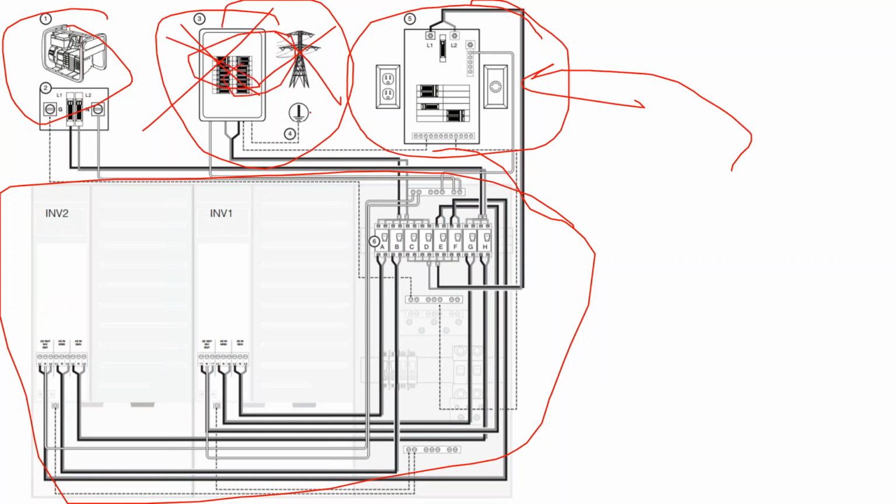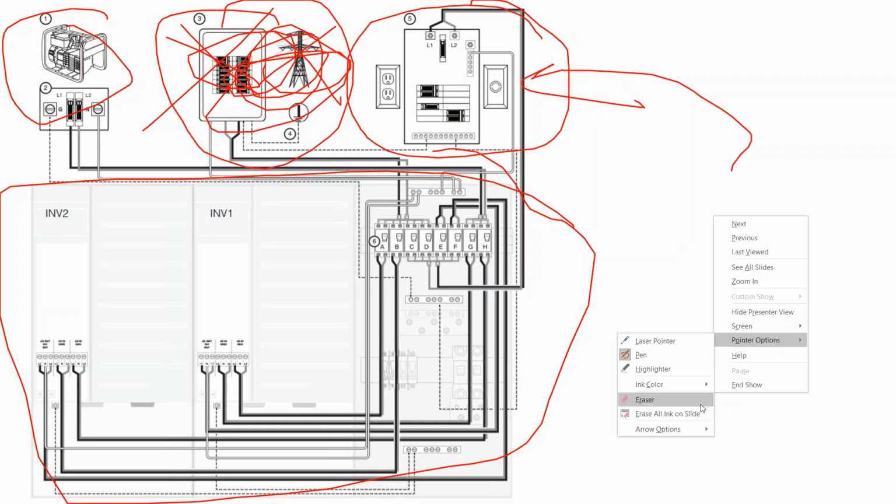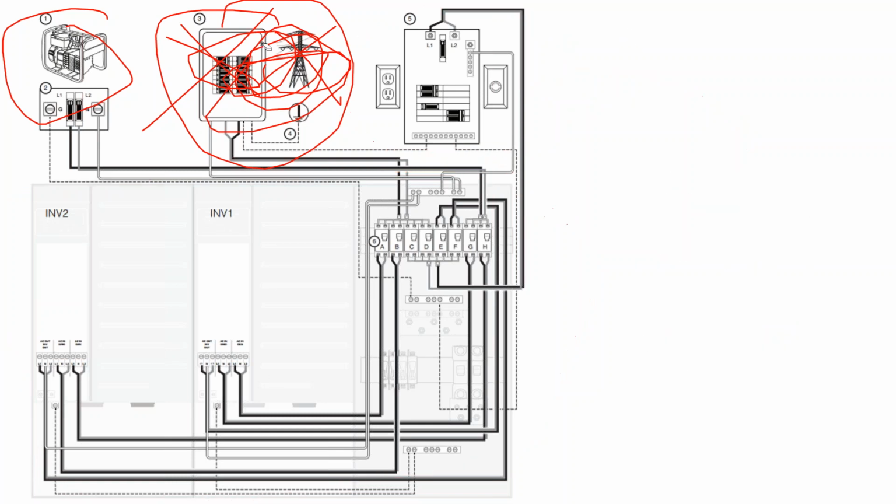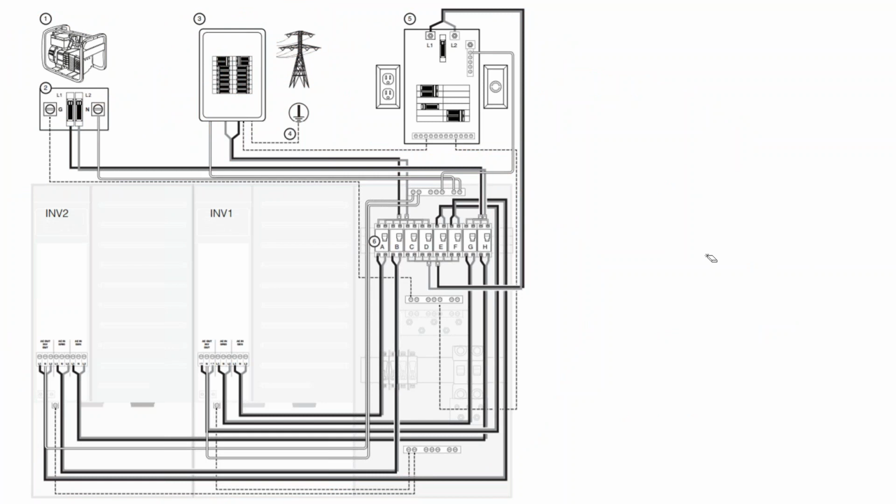So we're dispensing with this panel, and everything is effectively a critical load panel at that point. And the complication we ran into was, okay, well, we know in normal electric code, there's a connection from the utility that establishes a reference between your neutral wire and ground.